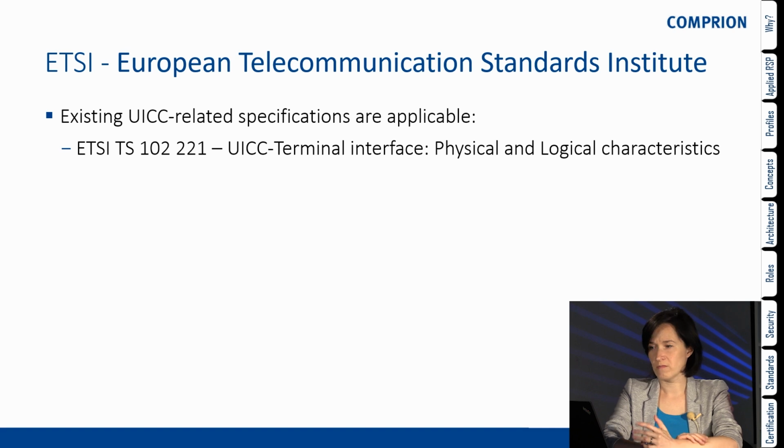This is the mother of all specifications. For the UICC, defining the platform, it is ETSI TS 102 221, defining the UICC-terminal interface, physical and logical characteristics. This is actually how we started to use the SIM card, by this specification.